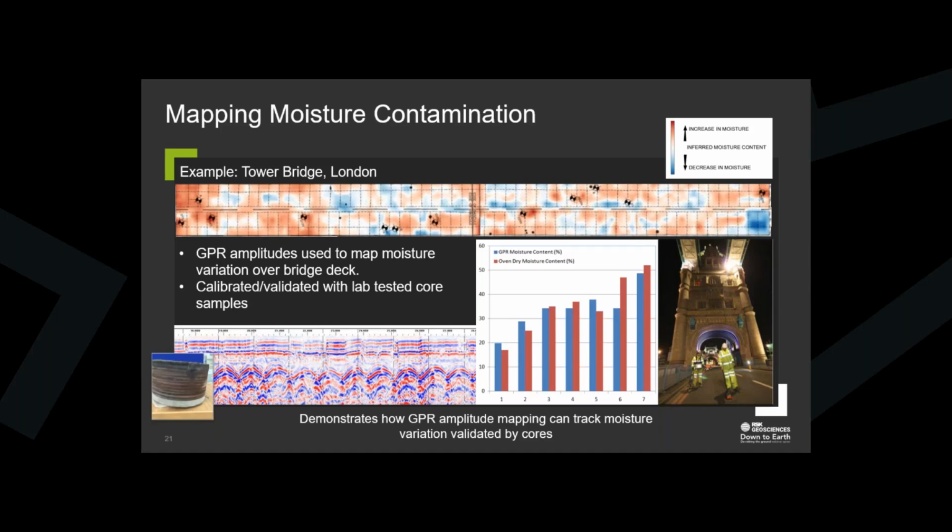We wouldn't normally try to offer actual values of moisture content from a GPR analysis, but we were, because we knew the specific elements about the wood itself, and we were able to apply some equations to come up with some. It was a very experimental kind of feature, but we were able to provide some estimated moisture content values, and they were generally in fairly good agreement with the actual values. So the client was very happy with that.